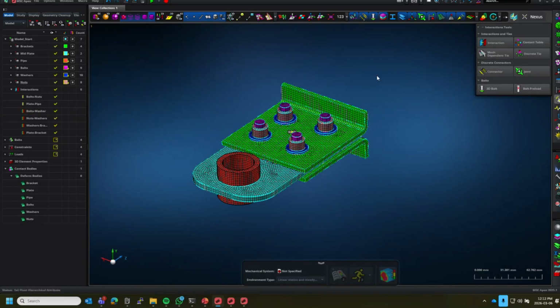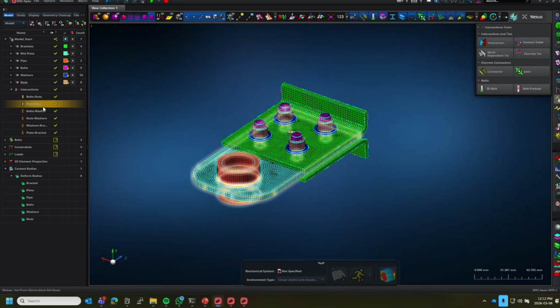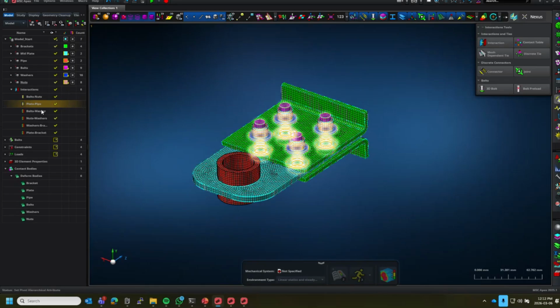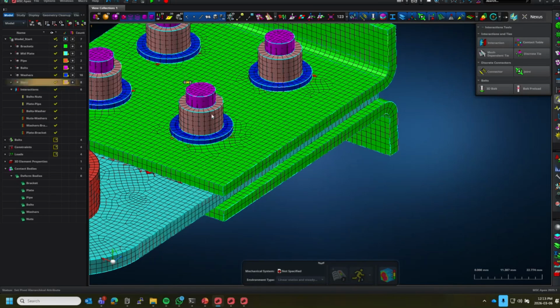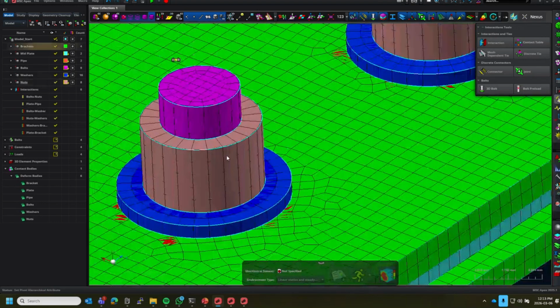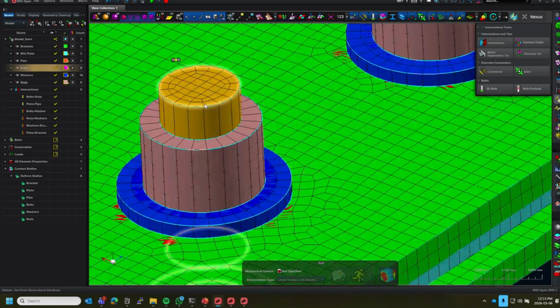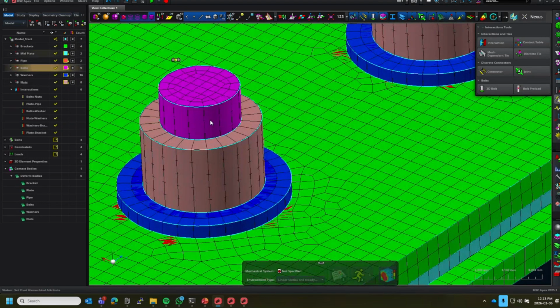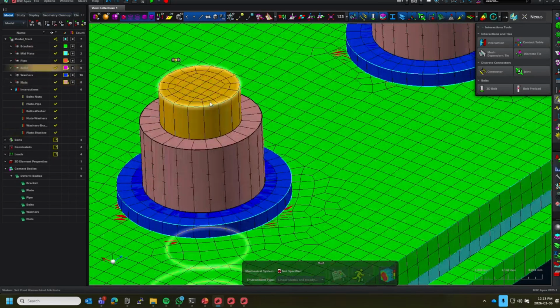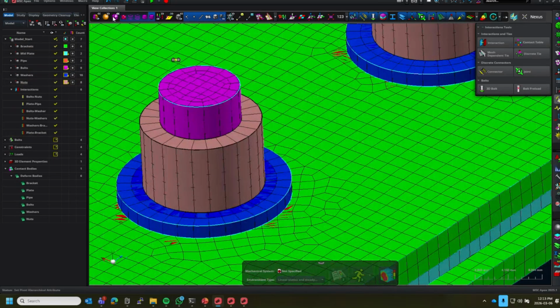Now, we've done it in this case while we were editing it, but especially if you just create it, it's then easy to go afterwards and check that it's set correctly and so on. Now, one thing we didn't actually look at, but something we have to think of, is that at this interface I'm using first order shell element, solid elements.